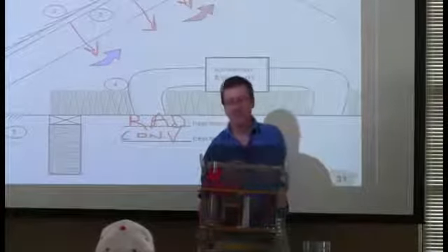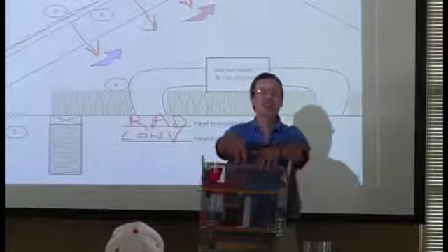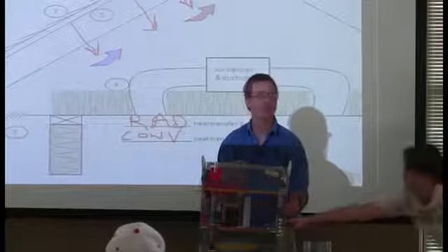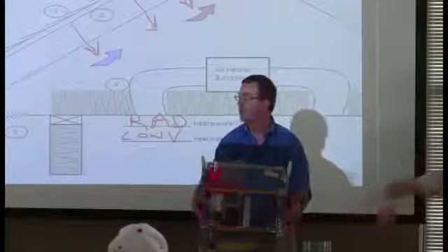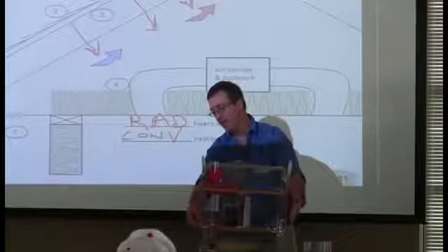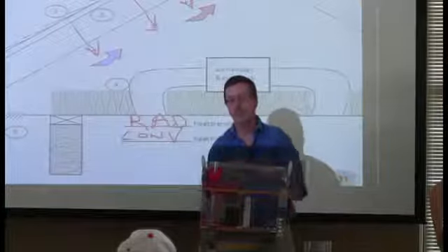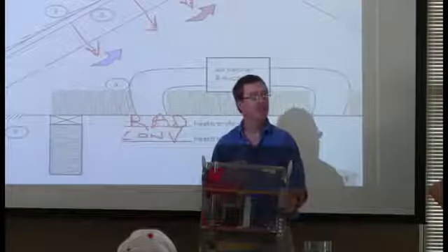If we turn on this fan, it is putting the attic under a negative pressure, but what else is happening to the house right here? Can you see the little doors? They were like this before it started. See, when they're turned on, it went like that. Here they're hanging down when I turn off the fan. They're pretty much hanging down. But when I turn on this fan, what does that indicate is happening?